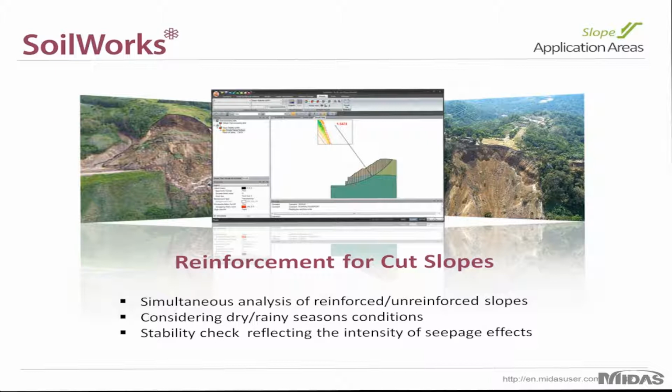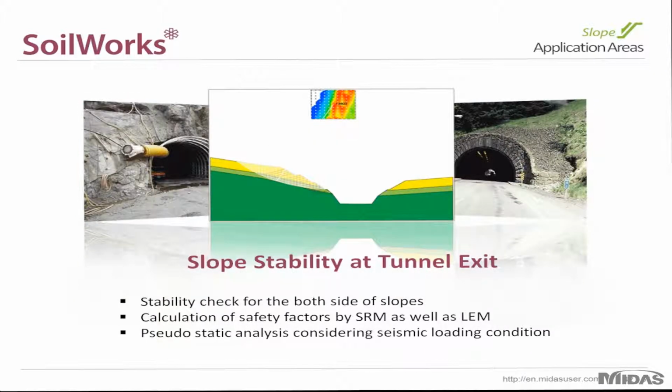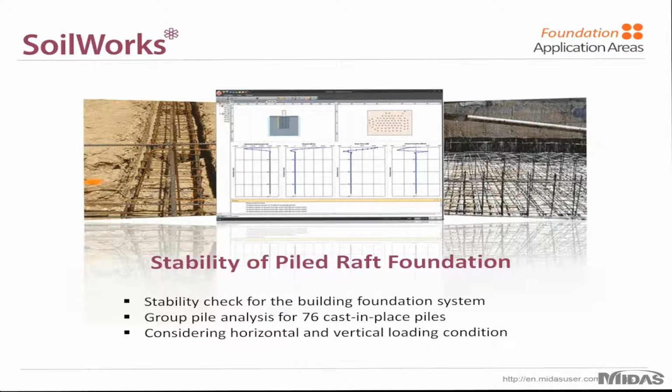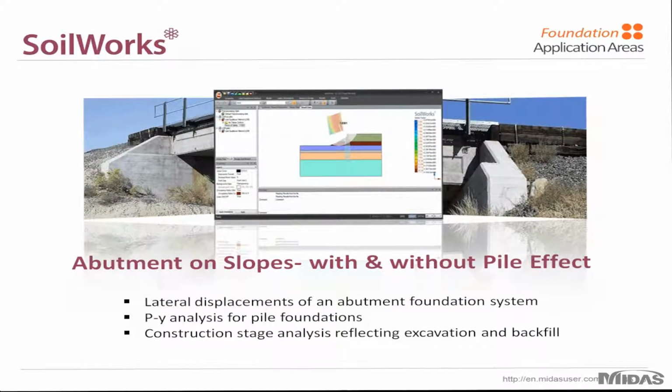Reinforcements for cut slopes, so you can very intuitively compare the effects your reinforcements will have on your slopes. You can also check for dry and rainy seasons using coupled analysis with the seepage module. Slope stability at a tunnel exit. Reinforced earth retaining walls. This is another type of project that the slope module can handle for you. Stability of a piled raft foundation.